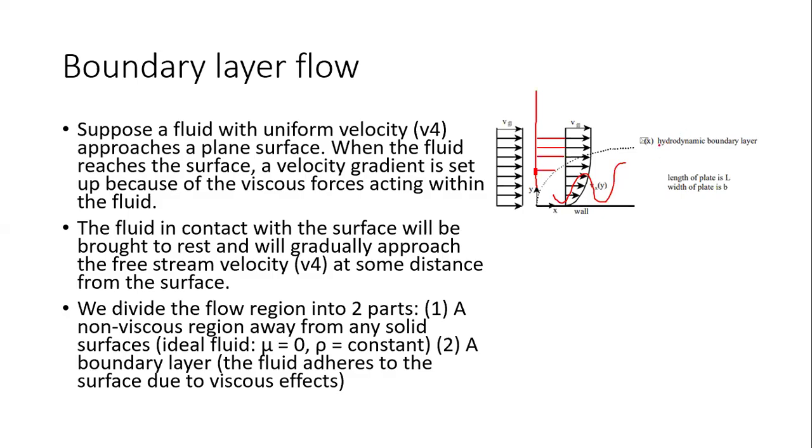So if we're working with a thermal boundary layer and not a hydrodynamic boundary layer, what we realize is that the wall here has its own temperature, and its temperature will affect the temperature of the fluid here. But once we cross that boundary layer, the temperature of the fluid is fixed. It's not going to change. It's not going to be affected by the wall anymore.